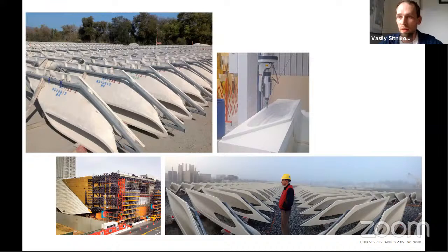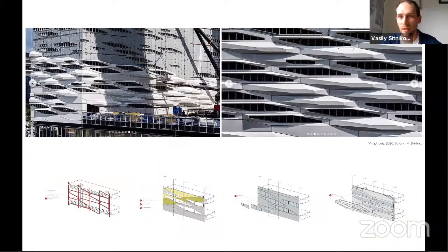However, the properties of glass fiber reinforced concrete are not quite superior, so it cannot really carry itself. It requires an additional stud frame at the back, a form of external steel reinforcement, for processing, maneuvering it on site, and installing. So it does come with certain limitations, also in surface quality, because to make an element of architectural design quality, one would need very skillful labor, right? It's not just shaping the backside of the element. It's practically a craft.